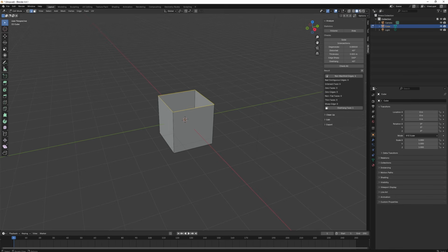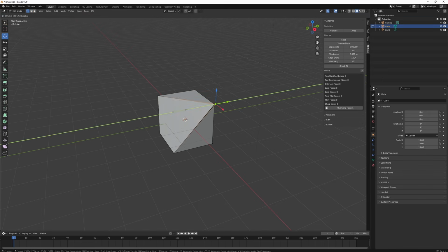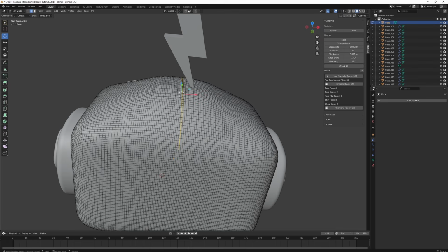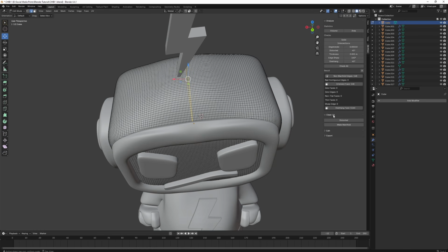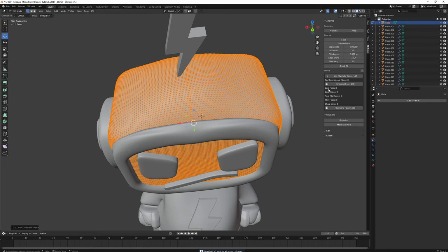It is obviously better to make sure they don't happen in the first place by ensuring you don't overlap the mirrored mesh. Gaps are normally easy to fix like we did with the robot's face frame earlier. Check all your objects to see if they are manifold. I have an overlap here, and while the Make Manifold button can help, it's not always perfect. In some cases you might need to delete the offending parts and fill them in like we did before.